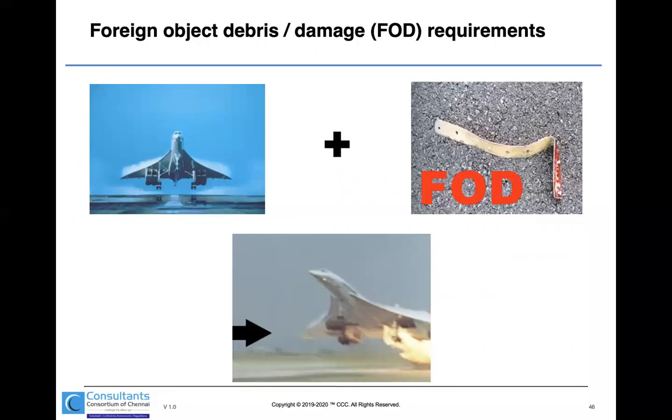It may be a scratch mark, it may be a fabric from our cloth. So it's mainly important in assembly. When you do any product assembly, that product is airworthy, we have to be very careful. The standard doesn't say you should have a clean room or a controlled environment and all. It depends on the product, depends on the engineering specification. So we should have a process for this FOD.